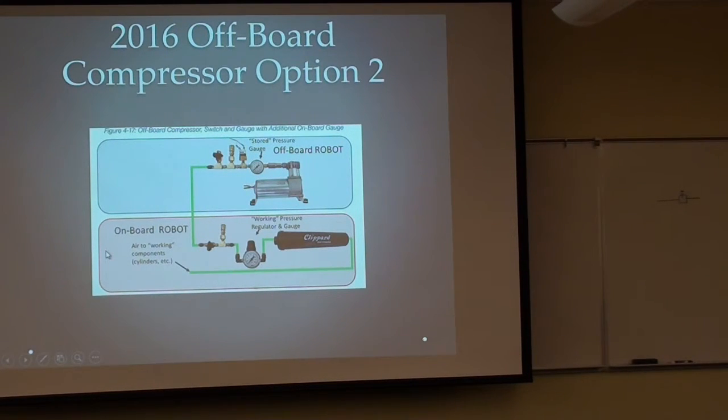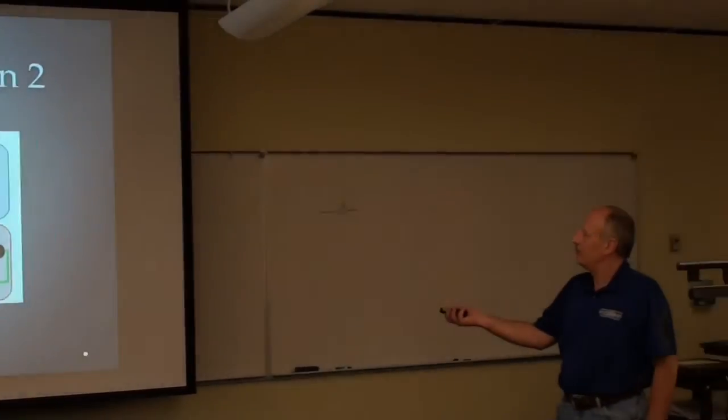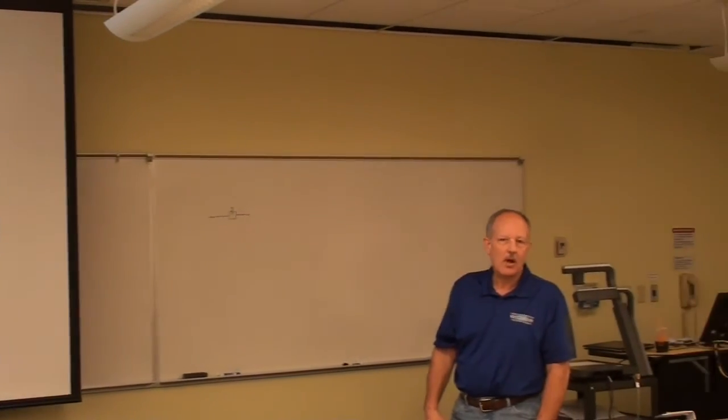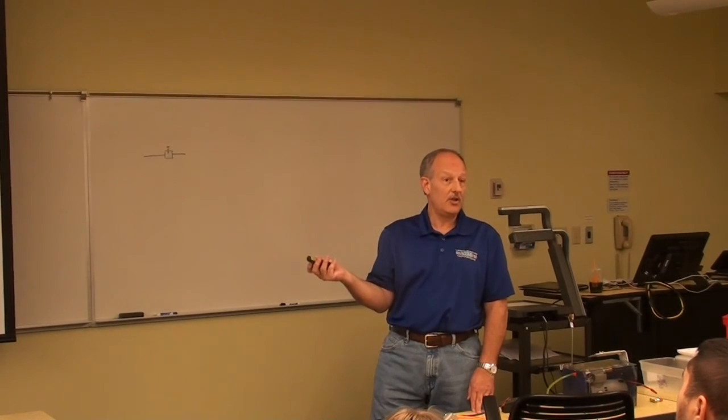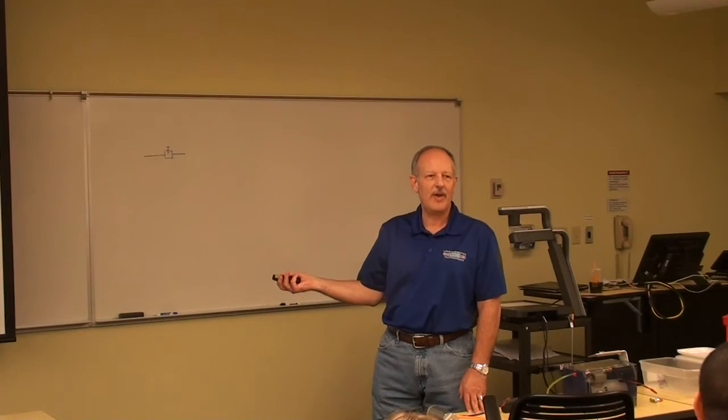What's the limit on the number of air tanks that you can have? Is there a limit? There wasn't a limit last year. There's not a rule against it. However, read the rules. You can put 100 tanks on your robot. Weight could be a problem, but that's not the problem we're getting at. It'll take forever. You'll never get it pressurized.